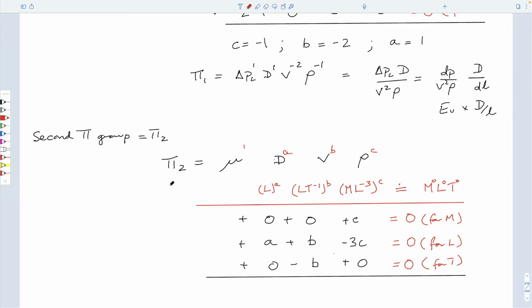What won't be the same is viscosity. Viscosity is in units, and I'll just pull it out of the hat here. You know how to do it, right? You know that viscosity is equal to tau over dv dx. And you know that tau is a stress, which is equal to a force divided by an area, and force is equal to mass times acceleration.